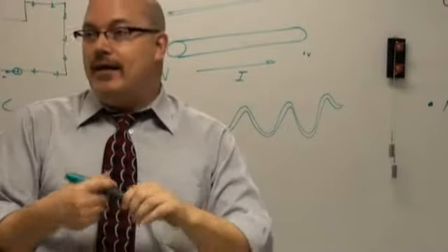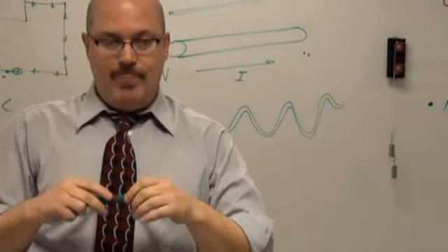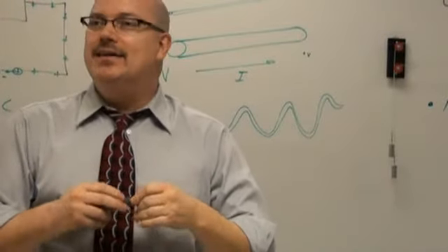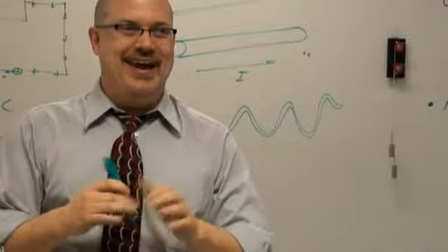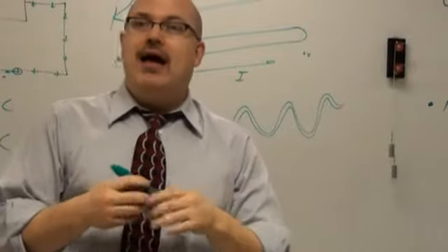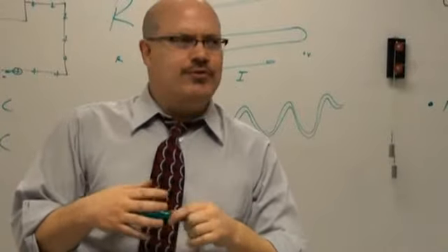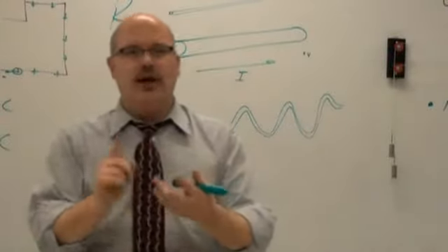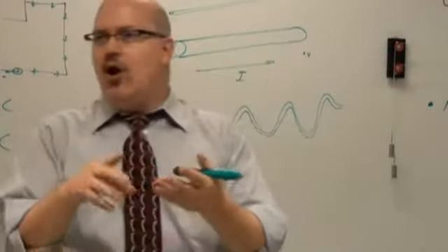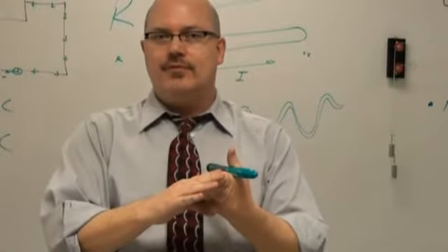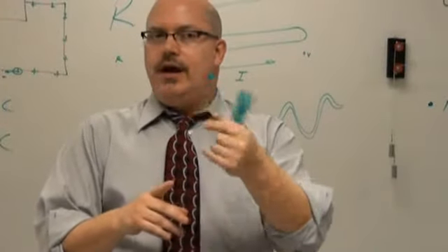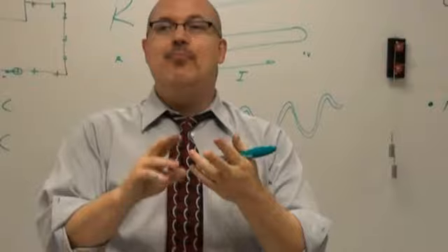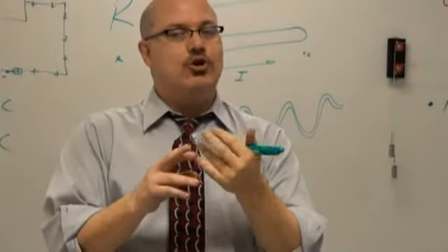Something else. What do you want your wire to be made of? A good conductor. Yeah, something not an insulator, right? Gold. Silver. Actually, I think silver is the best conductor. Gold, silver, copper, aluminum are all way up there. Most copper's the cheapest. So while it's not the best conductor, it has lots of good qualities.